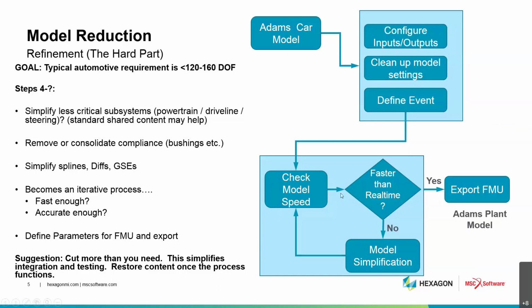At this stage, when you're going through this on your own, in a desktop kind of environment, I would recommend taking that down a little bit further than you might need to go to start with, so that you've got something that's a little more rock solid. You're sure it's going to meet real-time specs, and you can do the hardware integration with that kind of model. Then, if you've got a little bit of margin, you can come back around and add some compliance, add some extra fidelity back into that model.